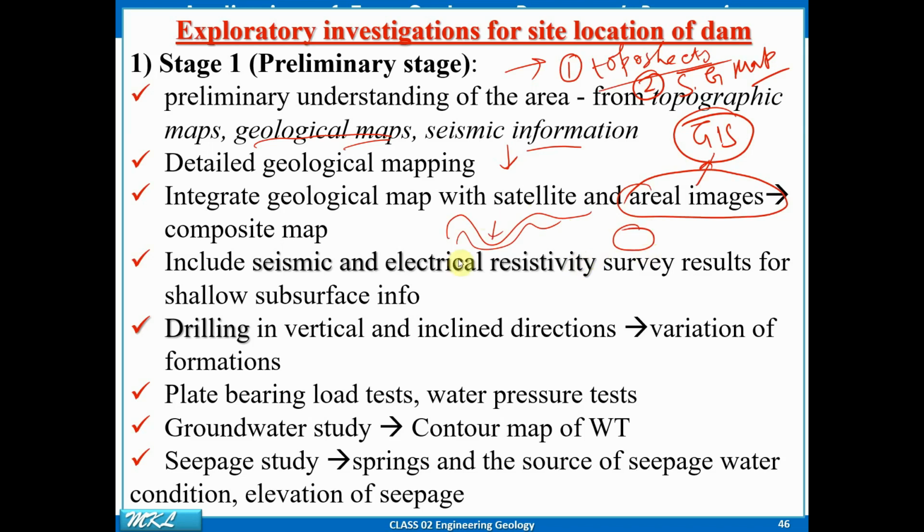After that, you will be doing some geophysical investigation. If people have already done it and published a paper, then you can follow that paper. Otherwise, you will be doing some shallow seismic and electrical resistivity survey. That is your geophysical survey. You will do it to understand the overburden and other layer locations, to delineate the shallow subsurface or shallow bedrock.